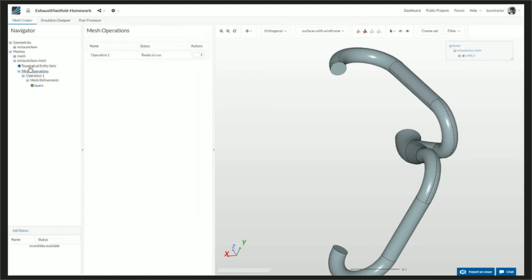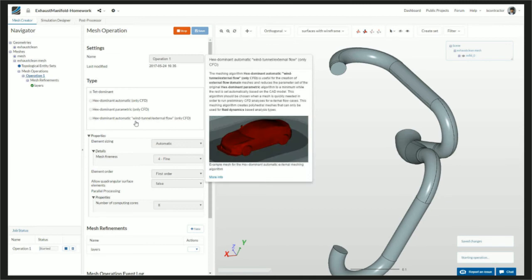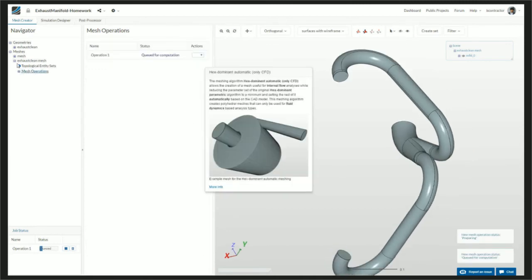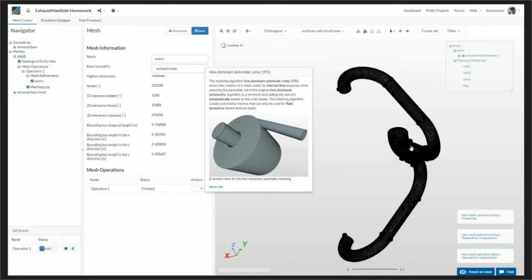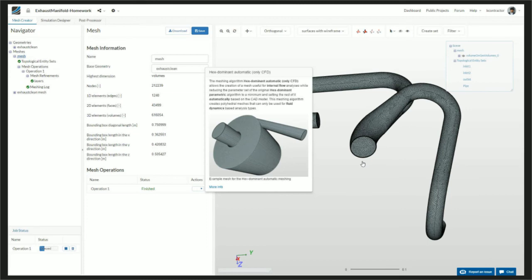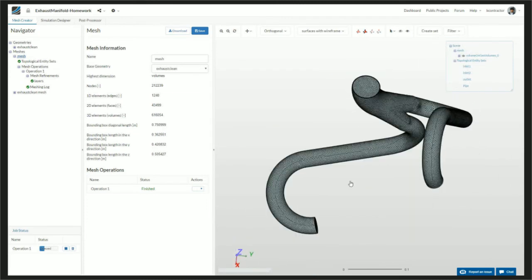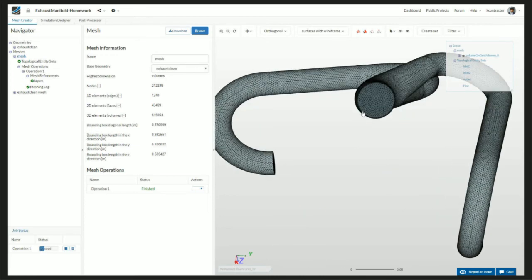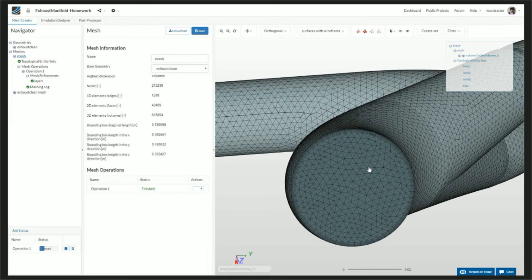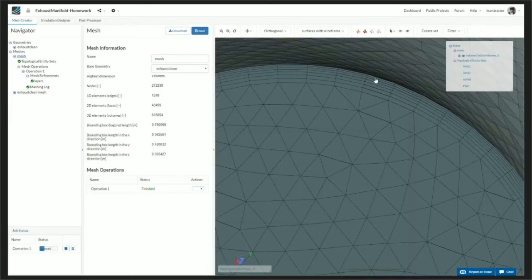So once we have set up all the parameters, let's just start our operation. And this would take around 10 to 20 minutes to complete. So you just look at the previously created mesh. So here we have our initial mesh. You can see that it's a pretty fine mesh for an initial simulation. And if you look at the layers, they're also pretty fine. And if you look at the first layer, it's around 1 millimeter.